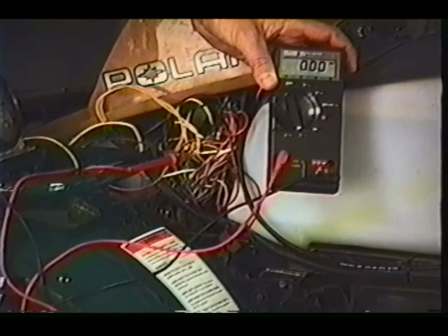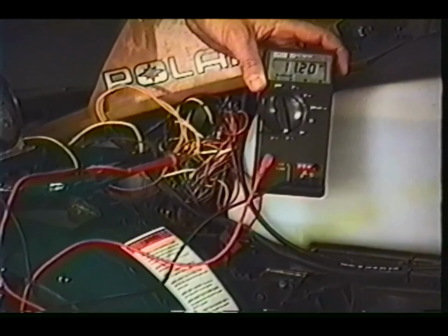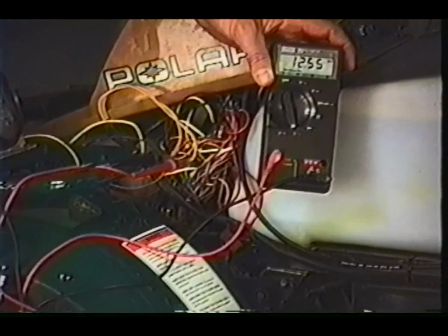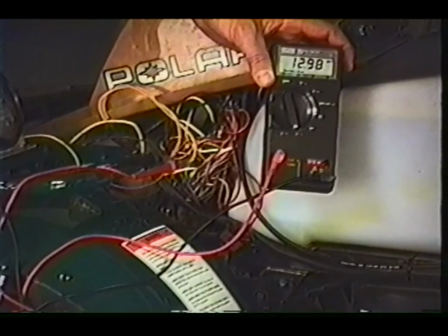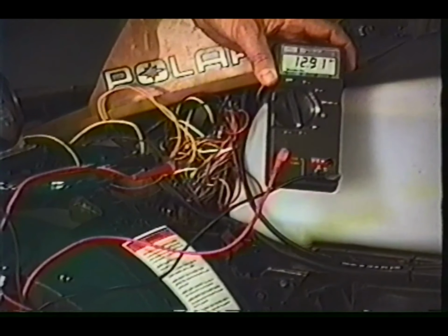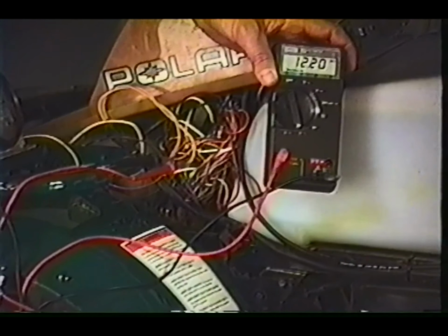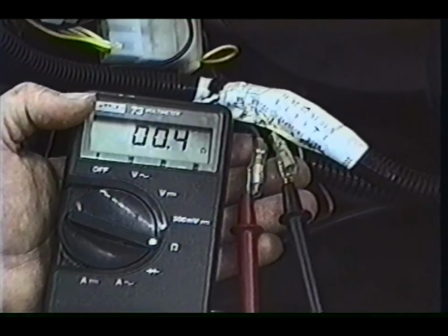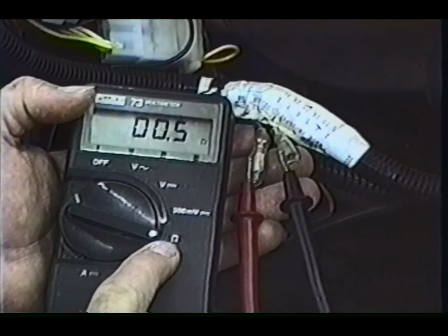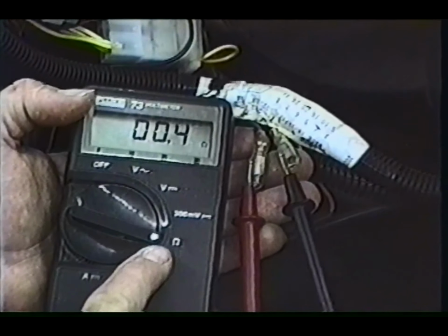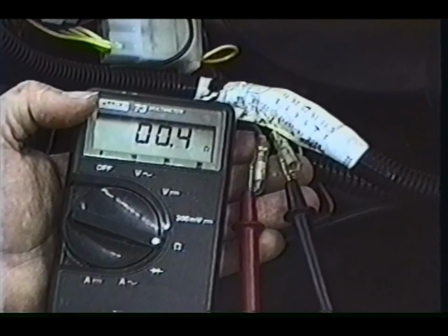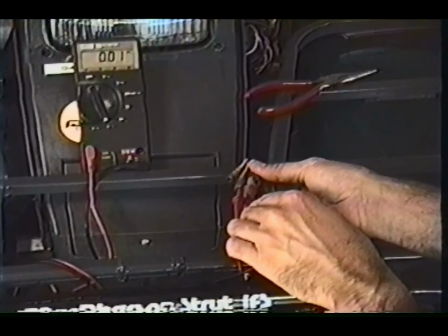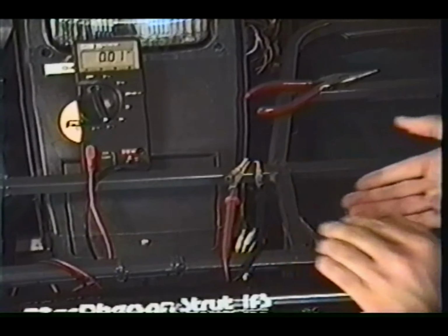Turn the engine off and move the red lead to the 10 amp outlet. With the selector dial in the AC amps position, start the engine and allow it to idle. Take readings quickly as prolonged current above 10 amps may damage your meter. Compare these readings to the minimum specs listed. If below normal readings have been observed, the coil resistance test should be performed to isolate a problem coil or related wiring. On 200-watt ATV alternators, like the Magnums, test output on the yellow and yellow with red wires.